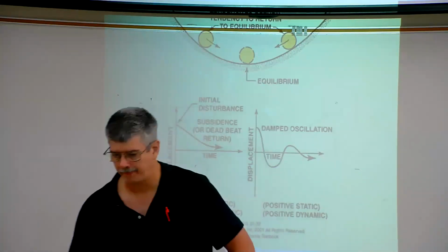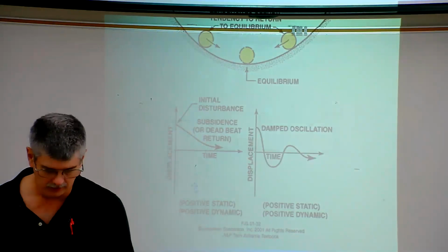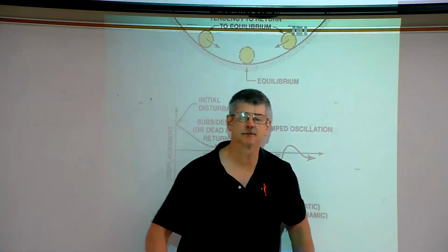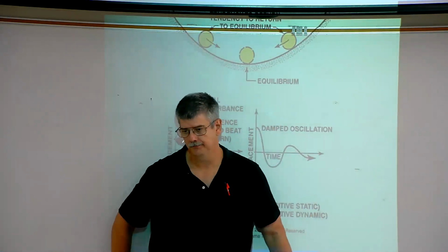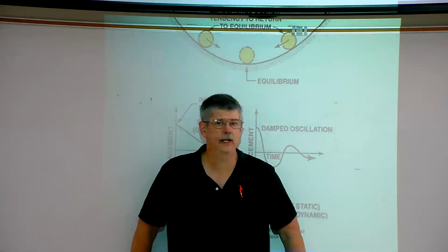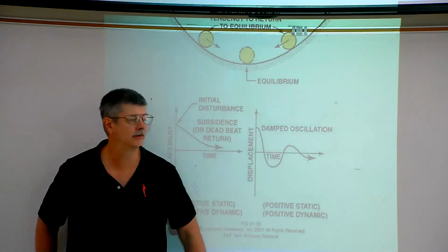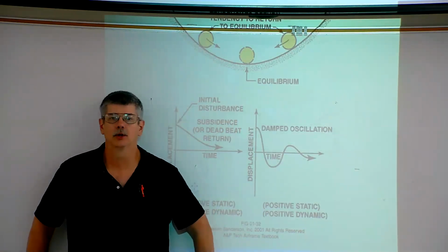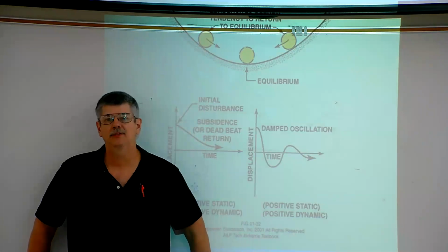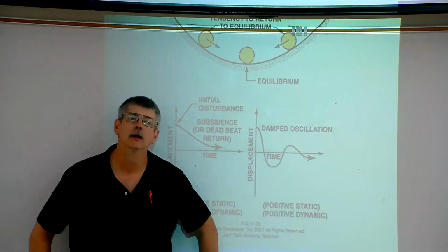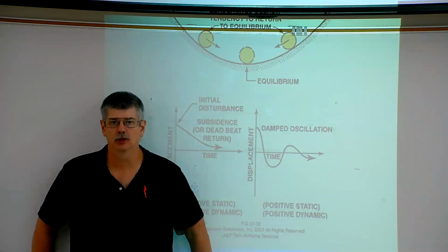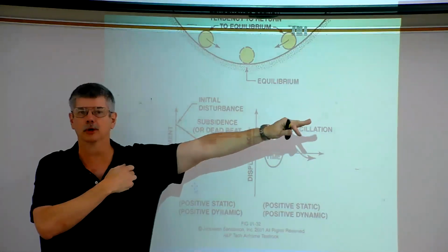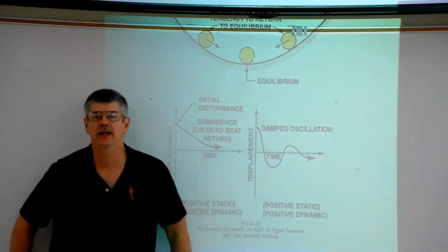All right. So we talked about the stability about the axes. What makes an aircraft longitudinally stable? And that is the center of gravity being forward of the center of lift, and the horizontal stabilizer. What makes an aircraft laterally stable? And the answer is the dihedral. The dihedral is where the wing tips are higher than the wing roots, and that is known as the dihedral.